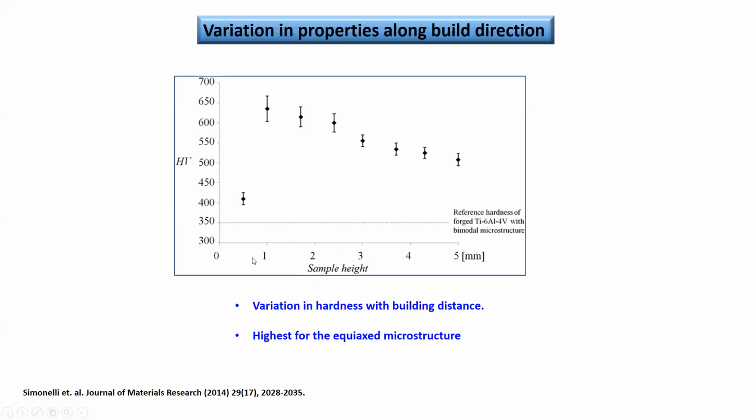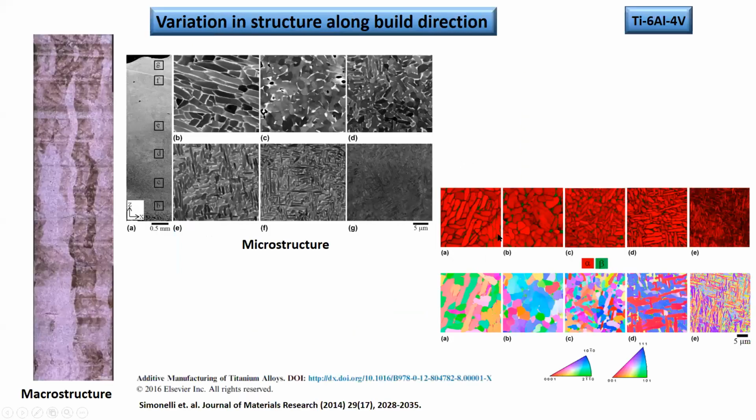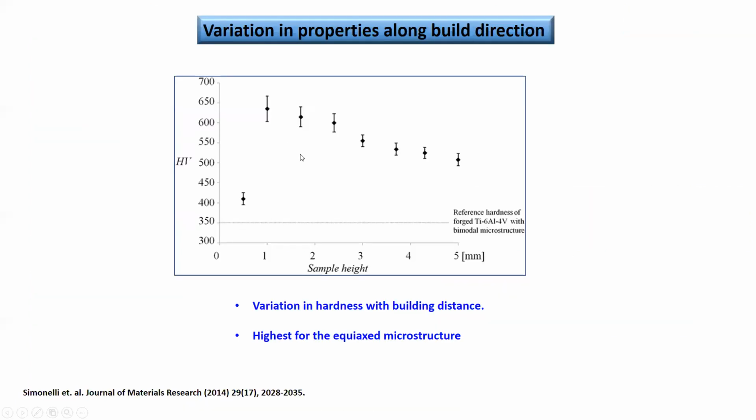Okay, by the way, the hardness is around 400 HV for the Ti64 which is conventionally produced. So additively manufactured, be it even the bottom or the top, is always having higher hardness. The structures that are forming usually are much finer than the one formed by conventional machining, and this is all related to the heat flow distribution. So eventually, due to additive manufacturing, we end up having improved mechanical properties of the material in most cases. Of course, there could be an anisotropy in the properties, and that has to be used wisely while we are using it for any application.